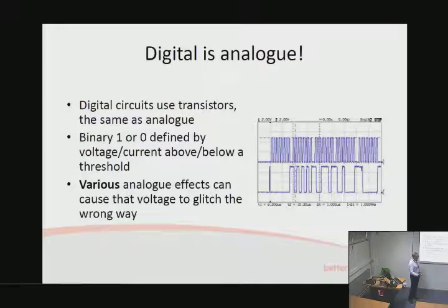So just to state the obvious over and over, digital electronics is under the hood analog. You can see here there's this apparently digital signal that switches on and off. We can get noise on that signal, and as we established in that previous slide, we can get rid of that noise again by switching, but if the noise is too great, it can corrupt the data very badly, and we can corrupt that information. And when it does corrupt, it can corrupt catastrophically.